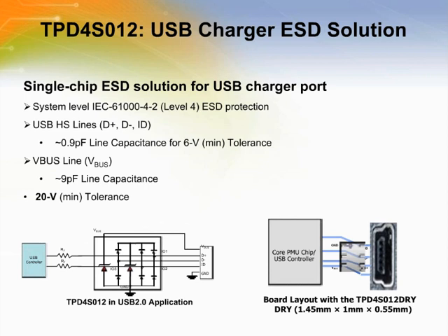In order to support different interfaces, the USB port needs to handle different voltage levels. For example, some chargers require the V-bus port of the USB connector to handle in excess of normal V-bus voltage per USB specification. The TPD4S012 offers combinations of 2 different clamp voltages to match the voltage tolerances of the different signal interfaces using the common USB connector.